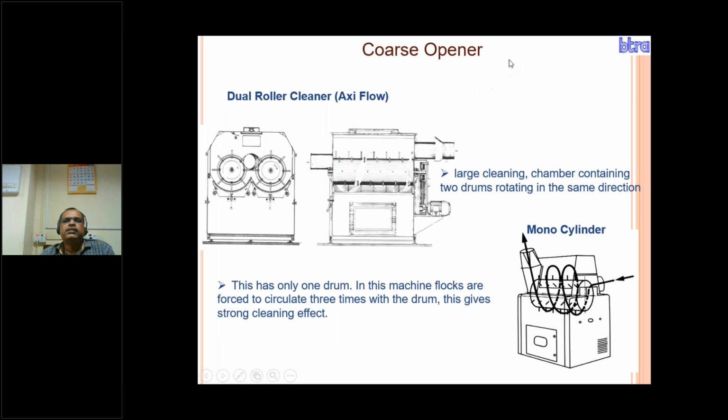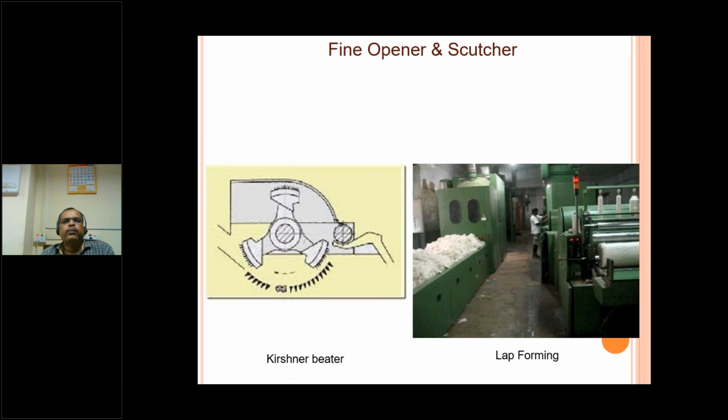And in the blow room, there are also different coarse openers, with blades, beaters, and suctions. Where there is a beating point, there is a suction point to suck the dust particles from the material. These blades and beaters differ to make a coarse opener and a fine opener. So these machines open and beat the fiber to remove the dust contamination out of the fiber.